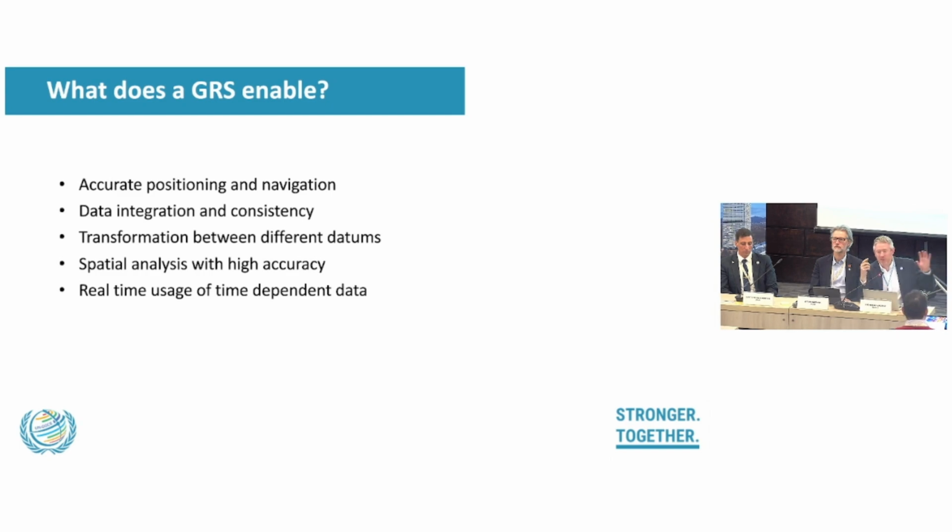But if you look at that whole integration picture, the purpose of modernizing that is because it enables a few things in your country. First of all, accurate positioning and navigation. It allows you to then be working in real time with the satellite data, as I mentioned before. That's the critical thing that you're trying to achieve. Making that connection between real-time satellite information and decision-making for you or for the government or for a user as easy as possible. That's the advantage of a modern geospatial reference system.